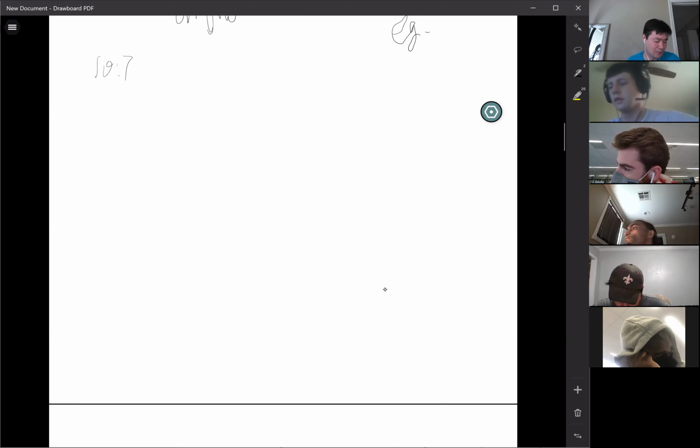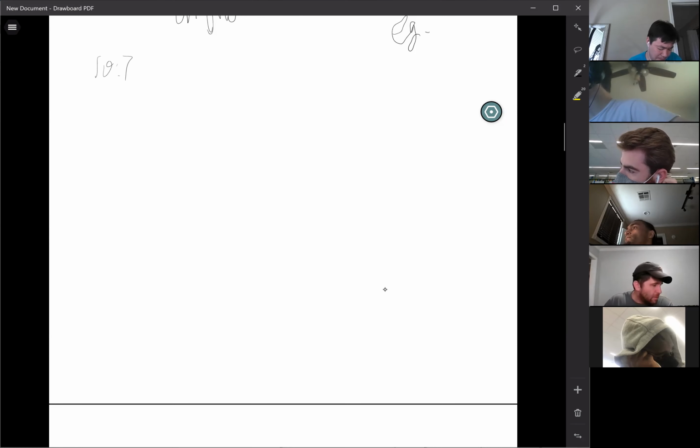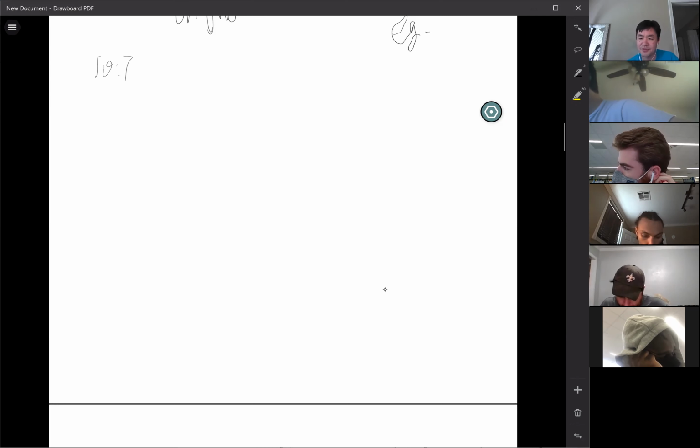Look at the example 10.7. There are 3 minor losses in there. You have 2 bends. Yeah, I think there are 2 bends there. So can you find the K minor loss coefficient for me? Don't look at the example, just look at the table. It gives you R over D equals 2. What is the K for the 2 bends in the pipe?